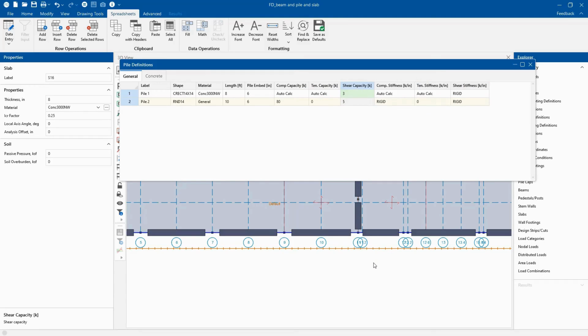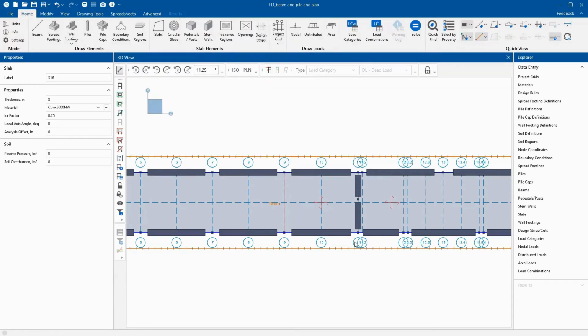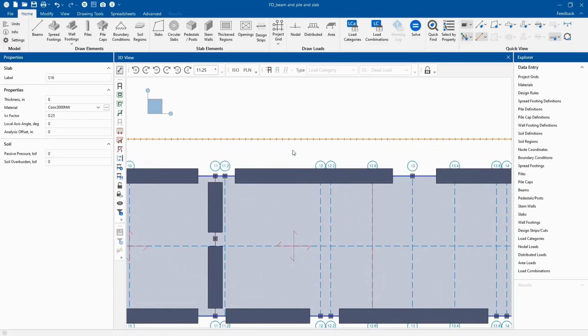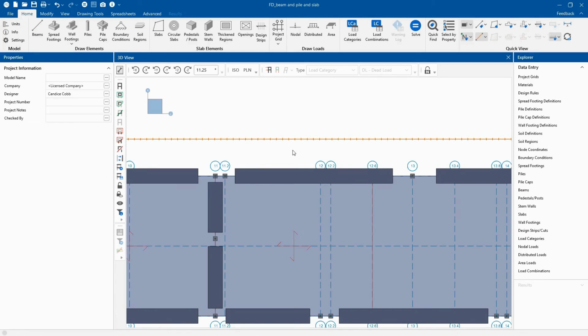One thing to note when you're modeling a slab like this, you're going to be looking at the center line of these beams. So if the perimeter of the structure was out here on the edge, it would be important for you to model it so that it has that offset slightly. So you could actually have the perimeter of the structure be represented properly. So we want to find that beam reinforcement.